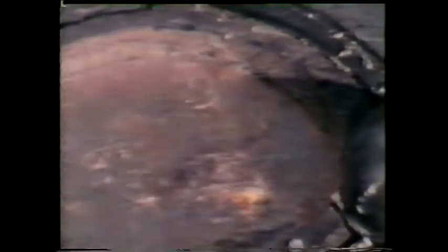Once molten, the metal can be shaped by casting it in a suitable mold. This is a sand mold. It's made in two halves, each half containing an impression of the component we're going to cast. A ladle is often used to carry the liquid metal from the furnace to the mold.